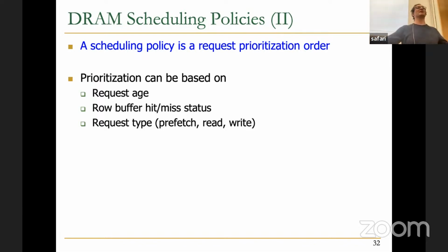If my write buffer is full, I have to push these writes out to DRAM. Otherwise, where am I going to put the next write? Right? So you need to switch to a mode where the memory controller does writes for a while. While the memory controller is doing writes for a while on that channel, it cannot do reads. Meaning now you're delaying reads that are supposed to be more critical because you have to do writes. So that means writes are critical also at that point, right? So these are the design choices that you need to make when you actually design a memory controller. One of the design choices, of course.